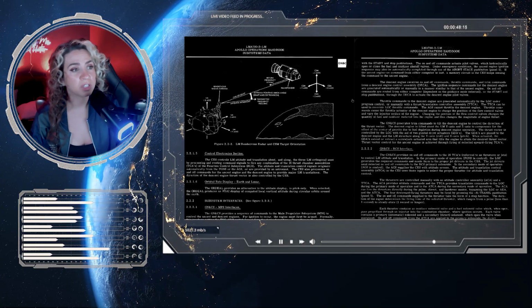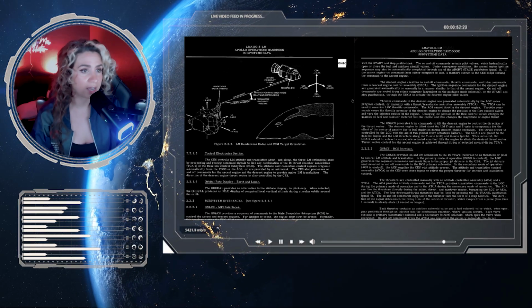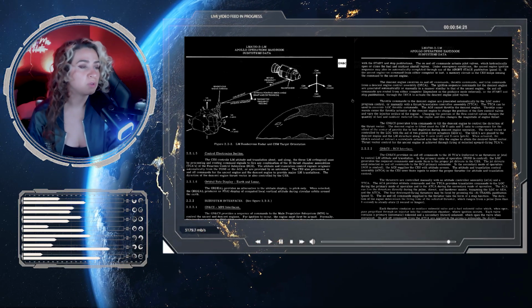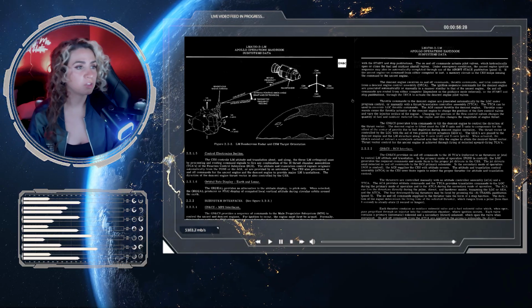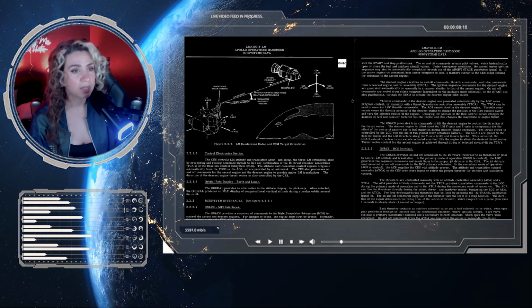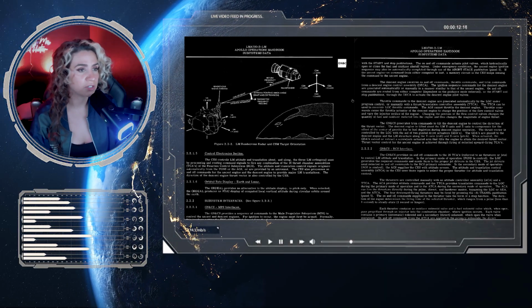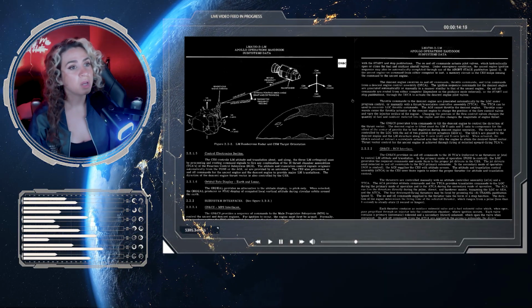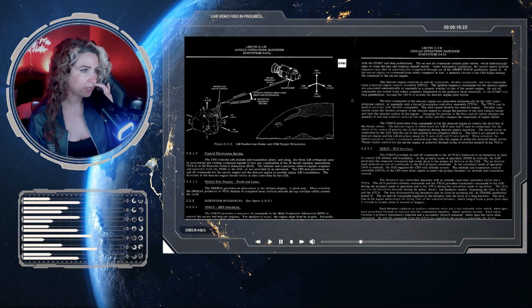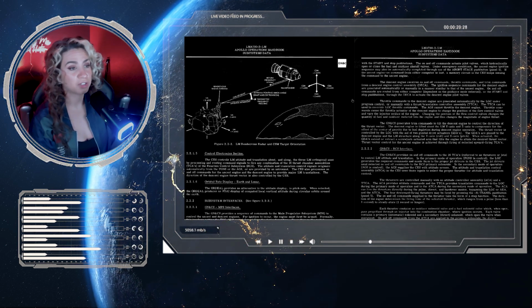or manually with the thrust/translation control assembly, TTCA. The TTCA can be used to override the LGC throttle commands. The AGS cannot throttle the descent engine. Throttle commands cause the throttle actuator of the descent engine to change the position of the flow control valves and vary the injector orifices of the engine.